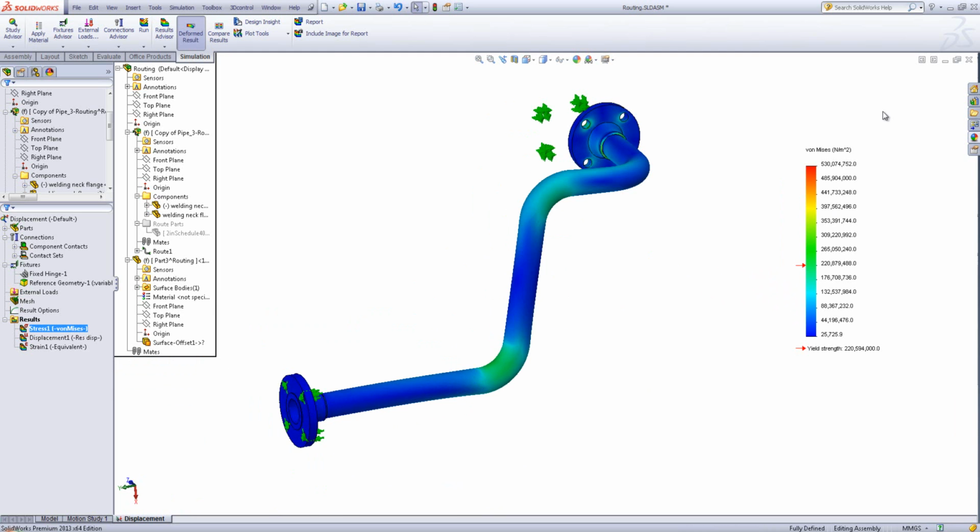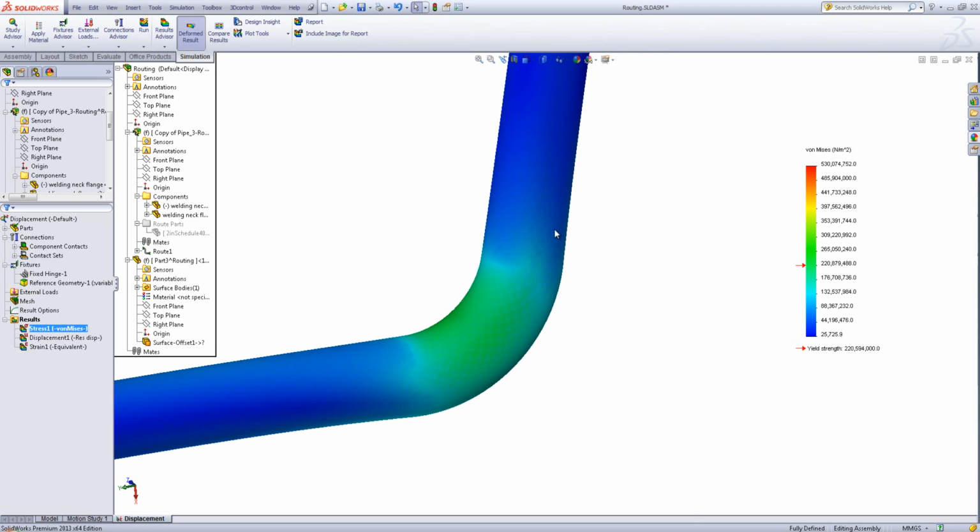But the thing I want to show you really is the type of stress that we've got here. So what we've got is a von Mises stress. Now the von Mises stress is a scalar stress quantity. It's a stress magnitude at each individual point location. So these have been extrapolated across the surface, so that now we've got a smooth gradient. Now that's all well and good. That's what we would typically use to analyse. So the von Mises stress is generally the most widely accepted stress value from finite element analysis for solid, blocky, prismatic geometries, but that's not exactly what we've got here.